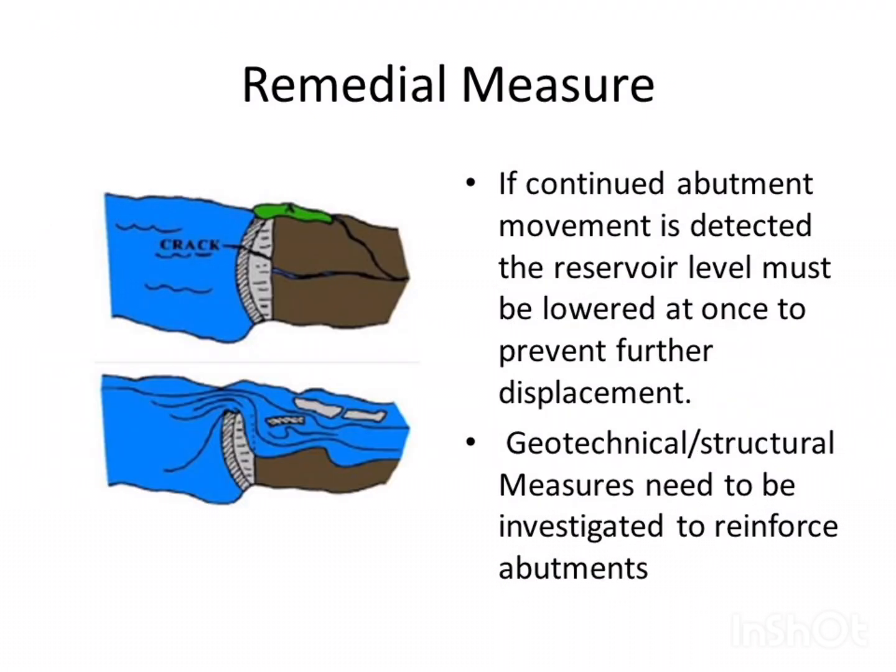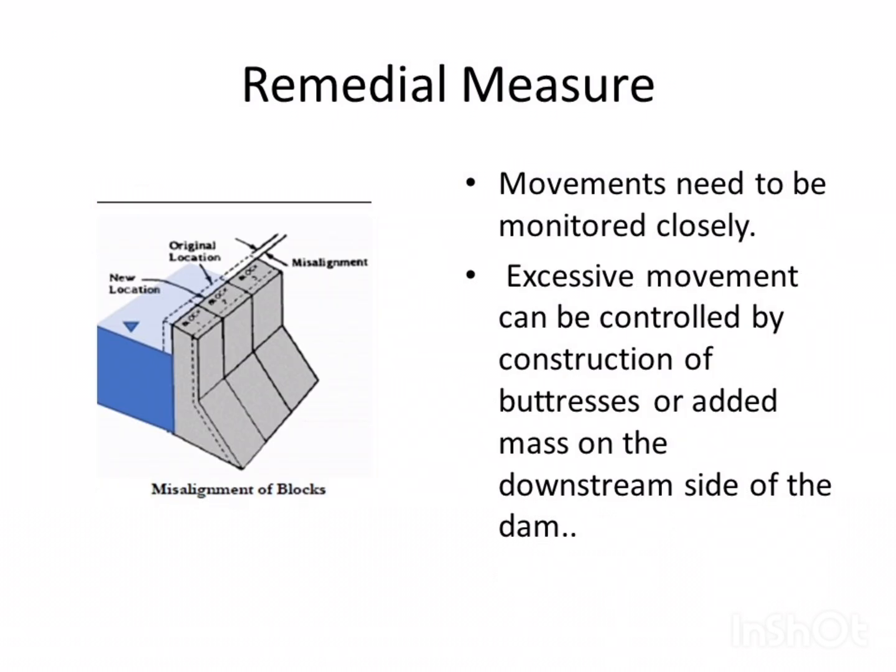If continued abutment movement is detected, the reservoir must be lowered at once to prevent further displacement. Geotechnical or structural measures need to be investigated to reinforce abutments. So abutments and foundations are very important. Here you can see that there is a crack due to the settlement of the abutments. So as the crack gradually increases, this may be catastrophic.